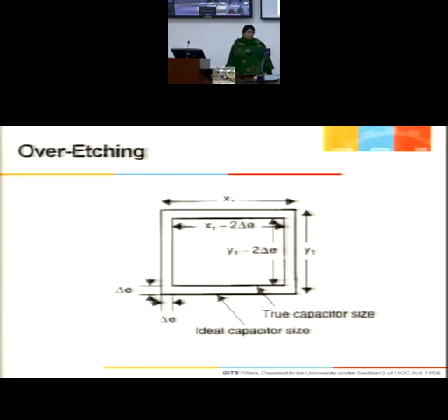That is the reason we choose a smaller unit component methodology. We are still able to retain the same W by L. Clear? Normally we choose square components because it is easy for us. Normally we choose square sizes, so 10 by 10, 5 by 5, 4 by 5. If square is not available, at the most we move on to rectangle. We do not go for any other kind of structure.